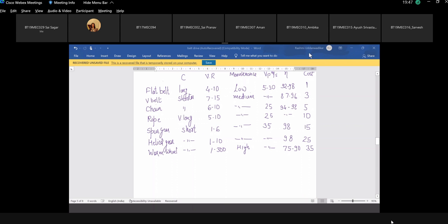Who is answering me? Deformation due to compression and extension. Yes. So while the pulley is rotating and the belt is continuously passing through it, it is stretched and then again compressed while it is moving the distance between the two pulleys. This relative motion between the belt and the pulley, and the stretching and unstretching, means the tension increases and then decreases, and increases and decreases. This stretching and unstretching of the belt is creep, which will reduce the life of the belt.